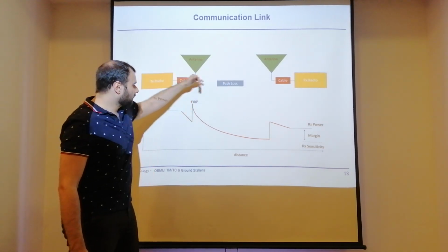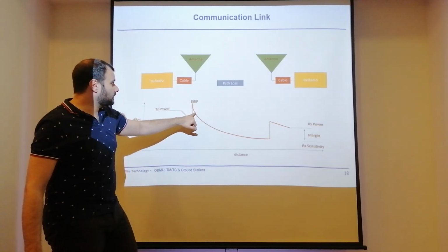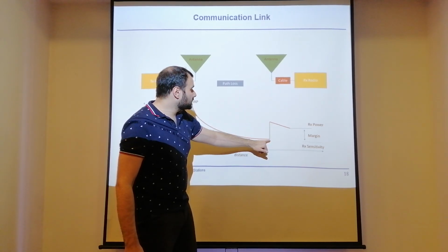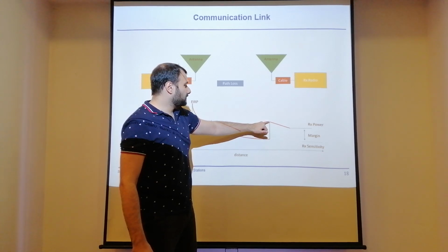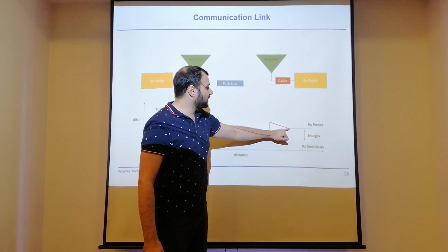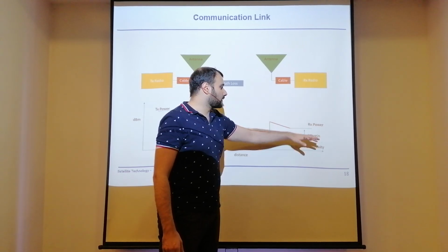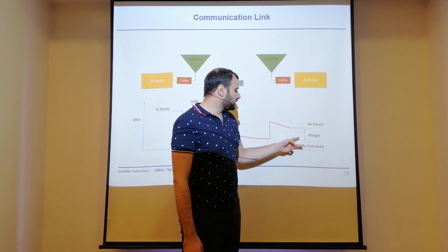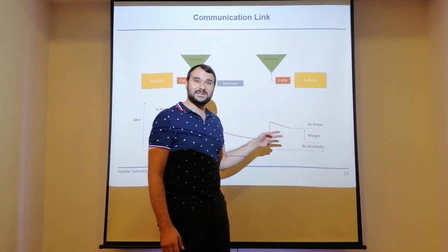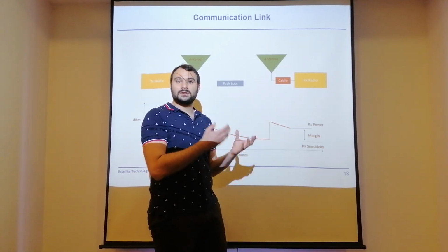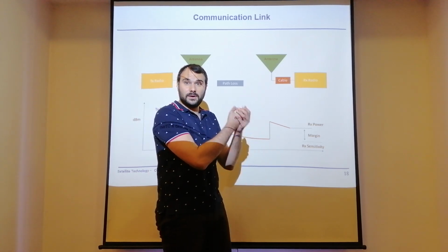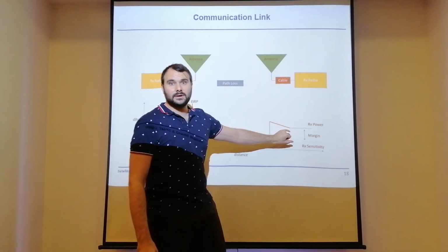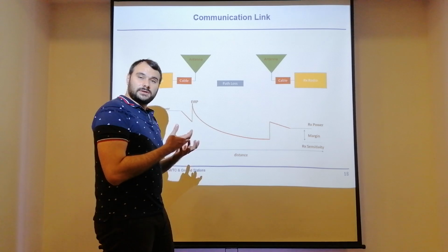And then we have our path. So this is the distance we need to cover. And of course, now we have a lot of path loss depending on the distance to our receiver. Then we have our ground station antenna here, and we have our antenna gain, which is again connected via a cable with some attenuation, and then we get to our receiver, our RX radio, and with a certain power level. And this power level needs to be above a certain threshold for our RX sensitivity, so we are able to decode, demodulate, and actually to have our signal there without too many transmission errors. And depending on the margin, we can actually distinguish the quality of our link.